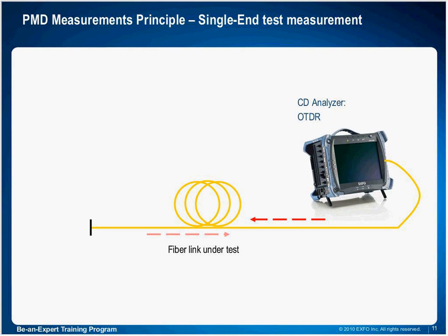Okay, the 5800, that's the dual-ended test measurement. That cannot detect faults in fiber. All it does is read the incoming light from the broadband source and measure different arrival times of different wavelengths.